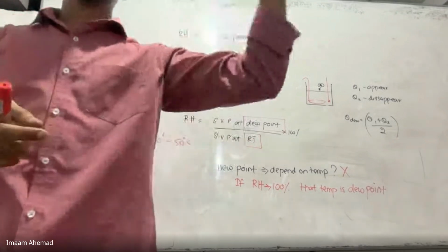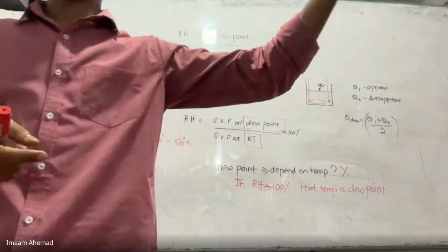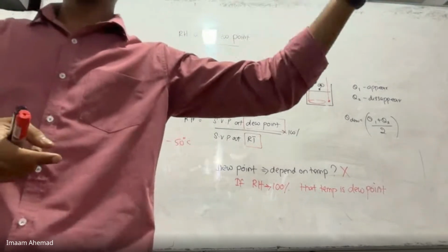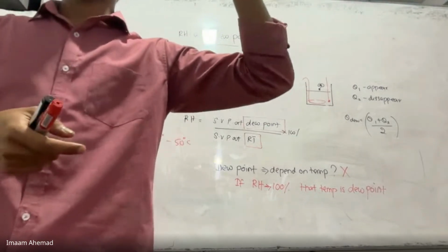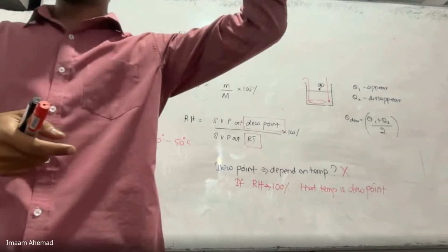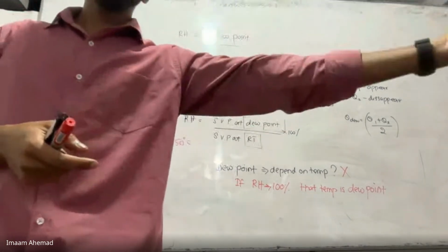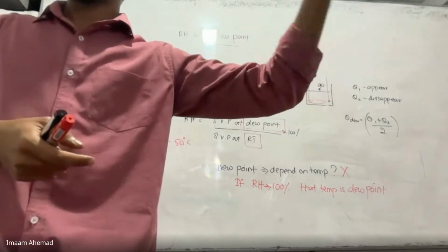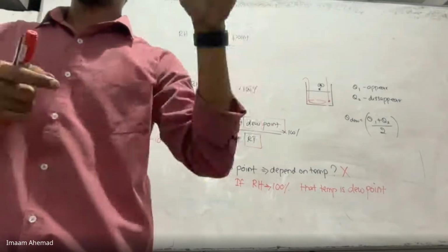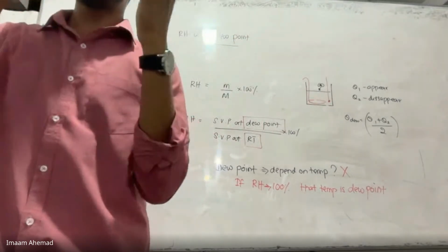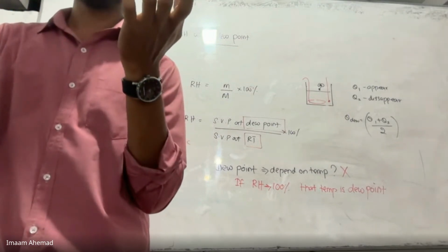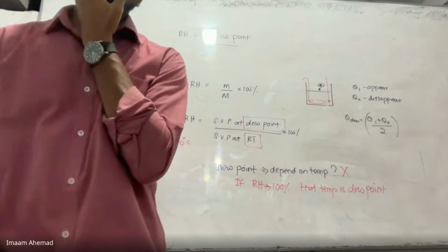The question that we discussed earlier, previous year, on the metal plate: the reason is that the dew point is above room temperature. So when we exhale, it will directly form the dew straight away, and that's one error. And also it will change the surrounding RH. Okay, so we have two errors.